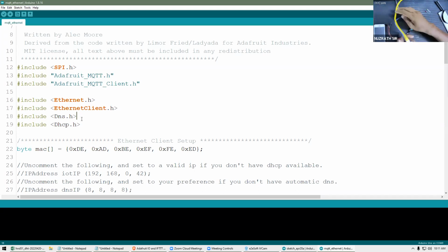I don't know whether you can see this piece over here. In this area, there are pins 13, 12, 11, and 10. Those pins are underlined in white like a box, which means those 4 pins are used by this shield. They are already used by the shield. And there are certain power pins from the Arduino that are also being used, and maybe that is how this particular board is getting powered up. So you need to keep that in mind, right?